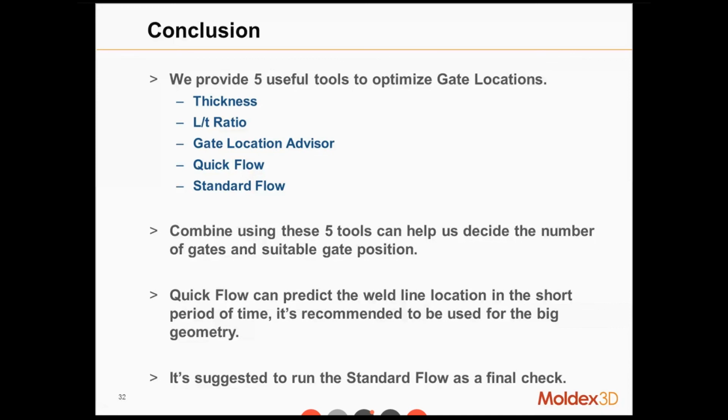So it's also always recommended for big geometry, such as the big car bumper or the dashboard. Finally, it's always suggested to run the standard flow to do the final check, as long as we choose a good gate design from the quick flow.